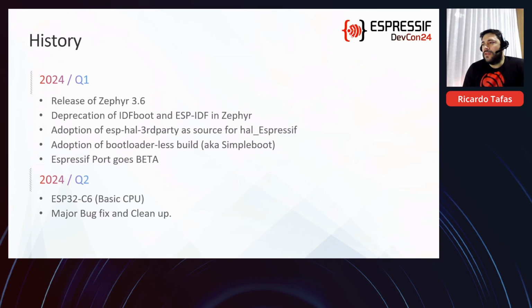Right after that, we managed to deprecate the IDF boot and the ESP IDF in Zephyr. So we moved to a new repository called ESP HAL third party, which is the source for HAL Espressif, which just takes the HAL components from ESP IDF. We managed also to remove the ESP IDF partition.